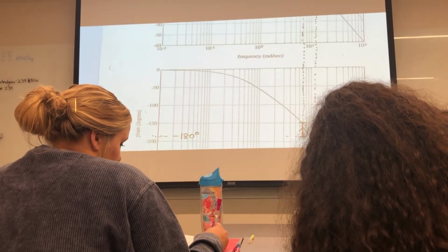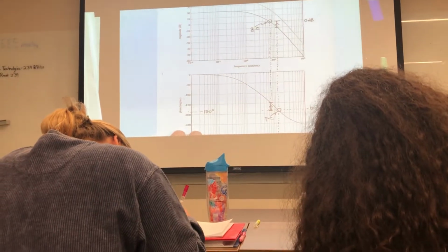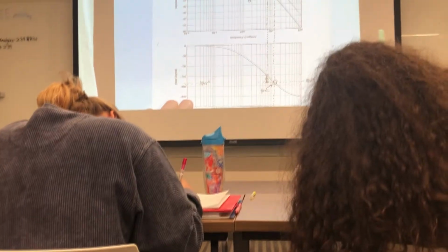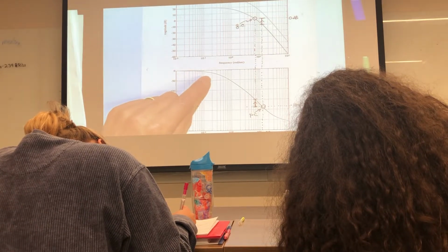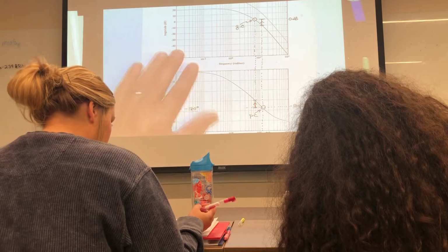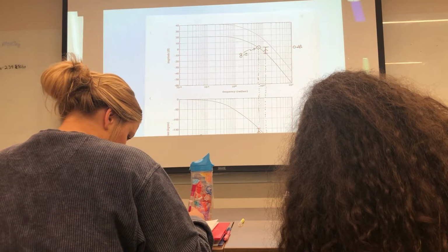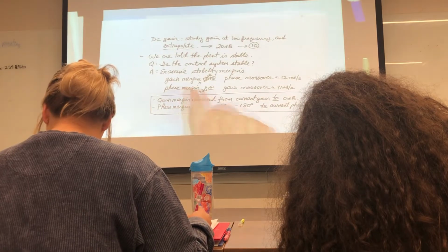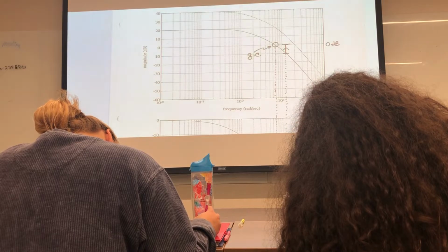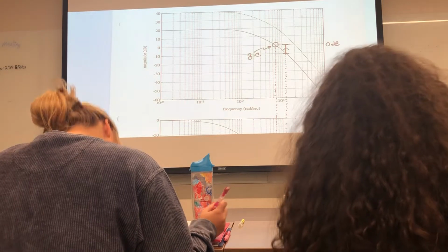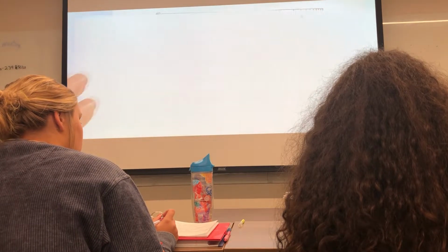Okay, so on this picture we have now done manually what MATLAB would do. If you gave it a model, if you knew the transfer function, you would enter the model and ask it to use the margin command, and it will draw these lines for you, and it will tell you up at the top the same information that we have just written on this piece of paper about the different margins. Let's also, real quickly here, sketch what's going on in the Nyquist plot.